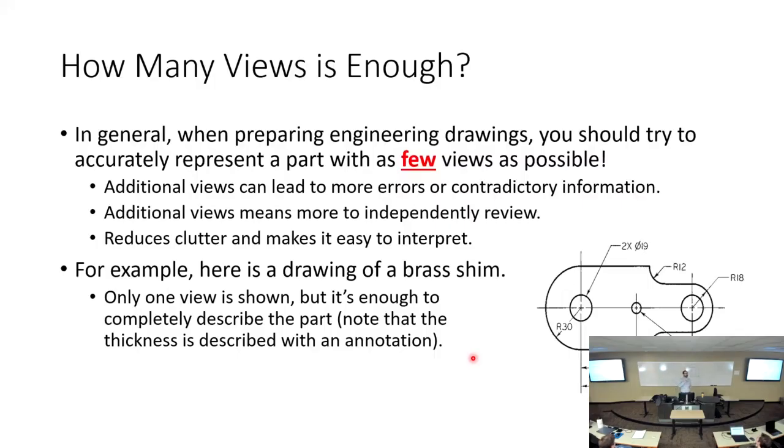I'm talking about a really, really simple part here, but what I'm saying is the more information that you put on an engineering drawing, A, the more stuff that you have to review and check, and B, the more potential for error. So if you don't need it, don't put it down. That's sort of my point. Now let's go back to this. So we needed 3. We also need this dimension. Let's call this 6 inches. Now that's 4 data points right there, right?